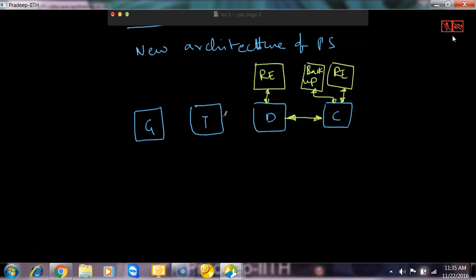So between transmission and distribution also, sometimes the power can enter from the distribution sector into the transmission sector. This is another problem. And here of course the power is unidirectional because by definition you are generating power, so you are injecting power into the transmission. Now there could be grid scale renewable energy. So again major wind farms or major solar farms may generate the power and directly inject the power into the transmission network. So these are the new things that are coming into the picture.